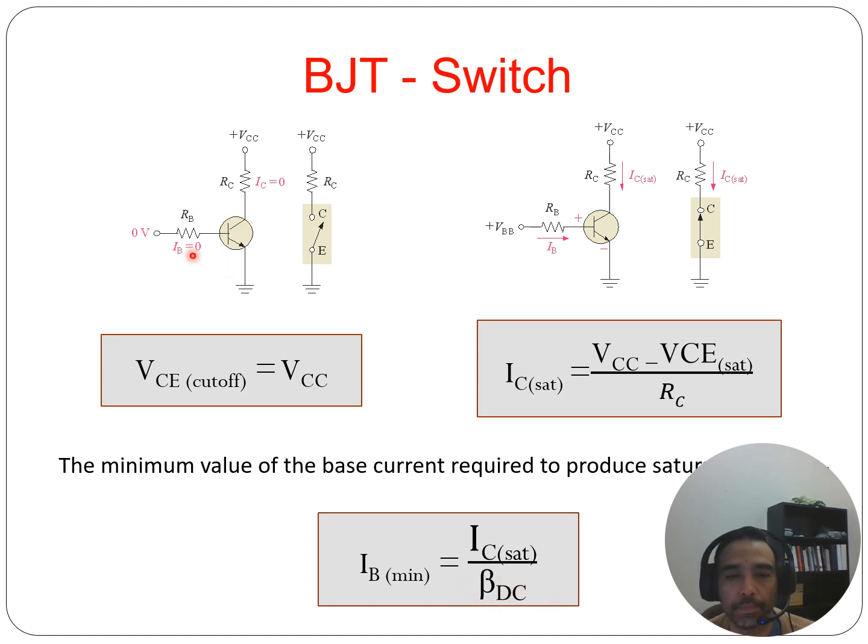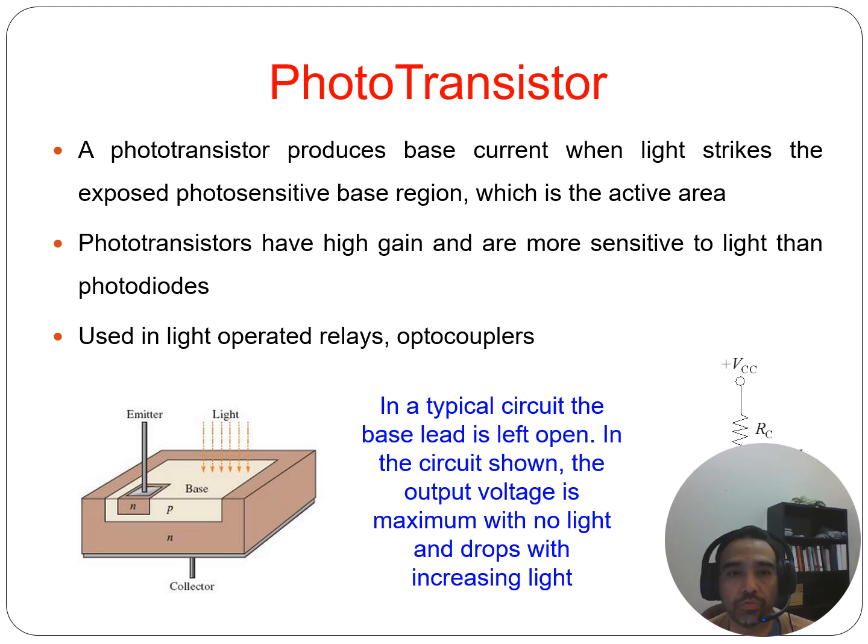Or again, if you know the part number for the transistor, you can look up the data sheet for it. And if they don't give it to you in the problem, they might expect you to calculate it. They're going to give you other information. In other words, they may give you saturation current and you solve for base current, and then you can use that to solve for BDC. Or they might make you run through a few steps.